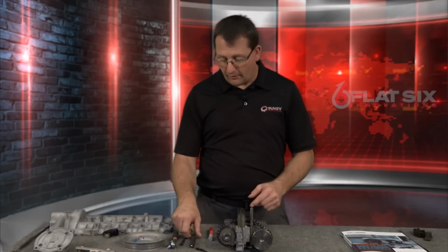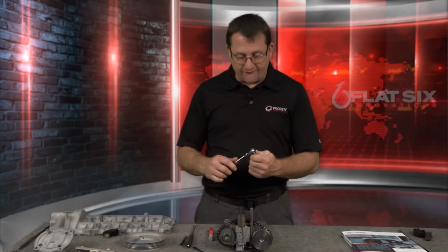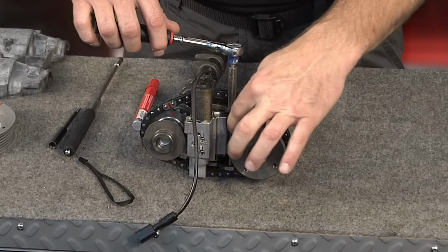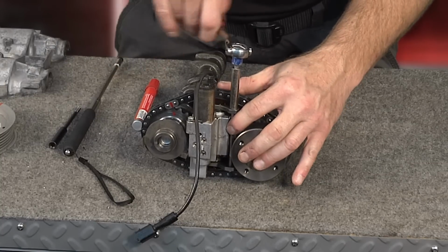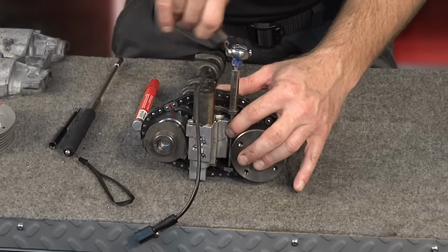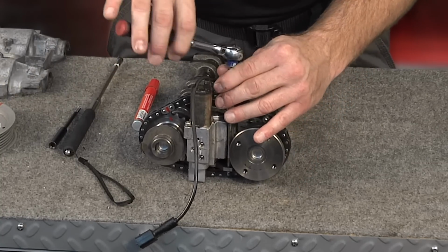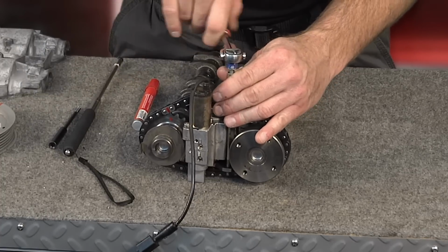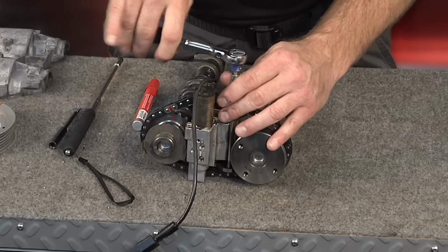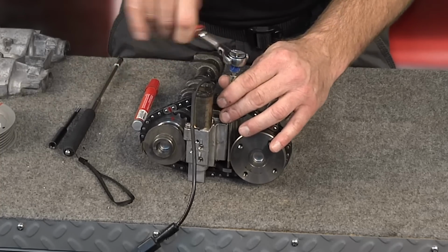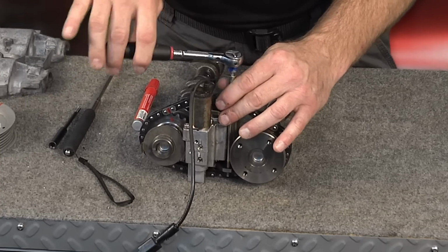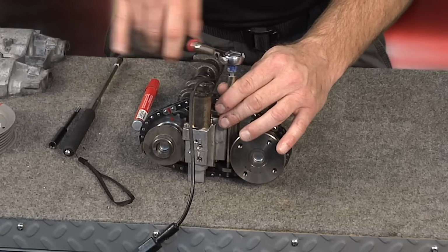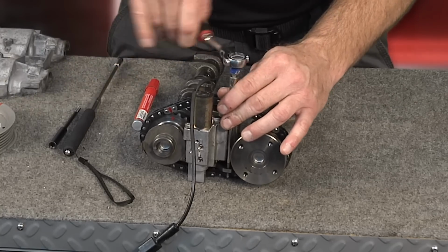So with that marked, everything's allocated. I've got a 5mm Allen here. I've got my right-hand threaded tool in this particular chain adjuster. And all I'm going to do is relax this, okay? I don't want to go crazy and be Goliath with this. I just want to compress it to the point where it starts to get tight, okay? And then once it gets tight, it allows me to pull all of this apart and access these chain guides.